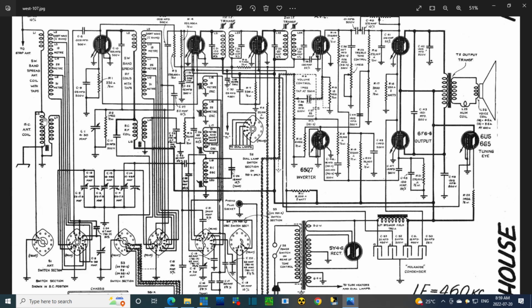The AM antenna signal's here in this coil, coming down on this wire, going into the switch. The switch is set to AM right now on the picture, so we can see it coming out on this wire, coming over here, meeting up with the tuning capacitors. Must be another way out of here. Oh, this one. So it goes up here, up on this line, and then it goes just through the capacitor, to the grid of the first tube. So you can see the AM signal gets to the grid of the RF. It doesn't bypass it, like I'm saying. In some radios, the output of this transformer goes straight over here and bypasses all this stuff. And then here's the AM coil here too.